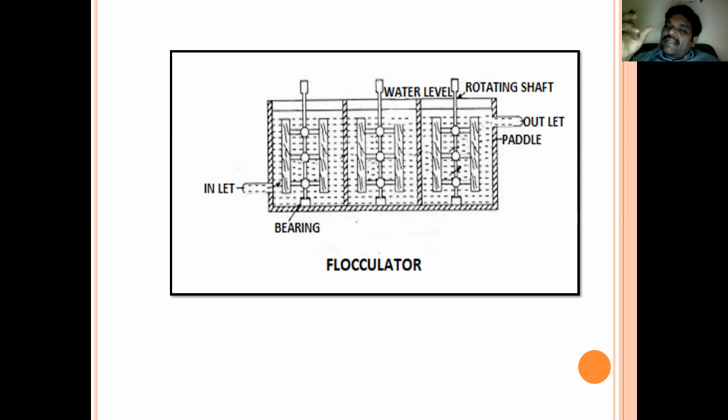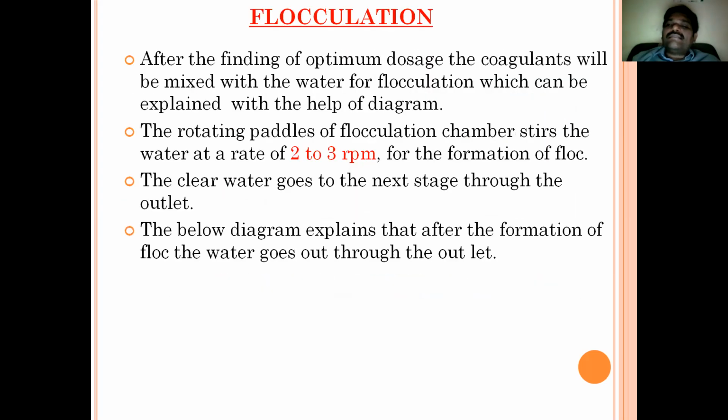What is the floc here? The fine colloidal particles which are unable to settle will mix with the floc, or else the foam, that will be taken off. See, the heavy particles settle at the bottom, and the particles unable to settle mix with the floc and reach the top of the water, and they will be taken off from the water by using mechanical scrapers. Understand? This is about flocculation.